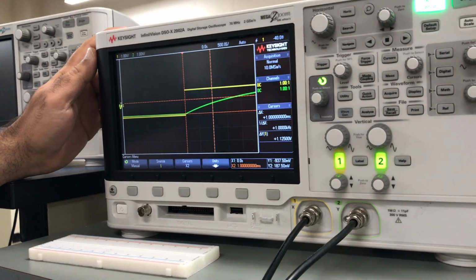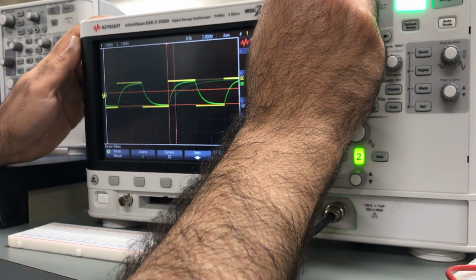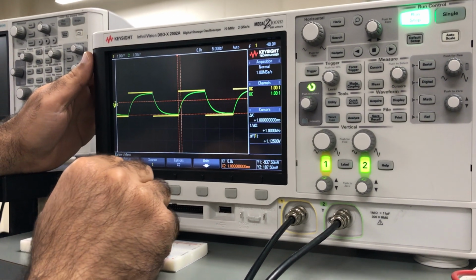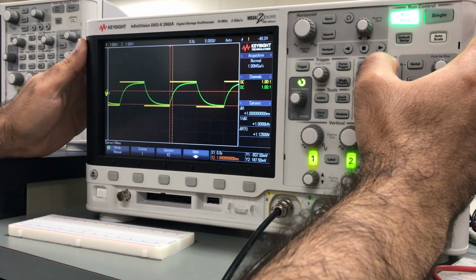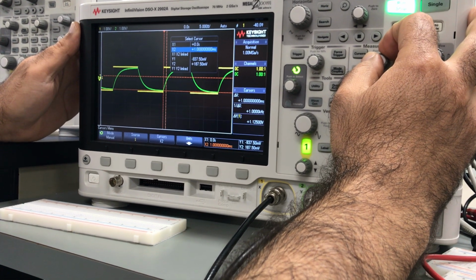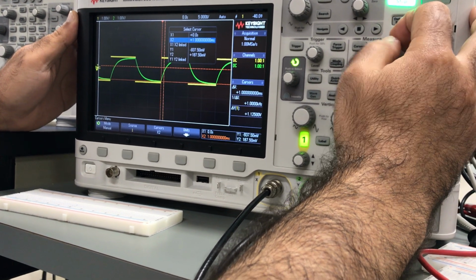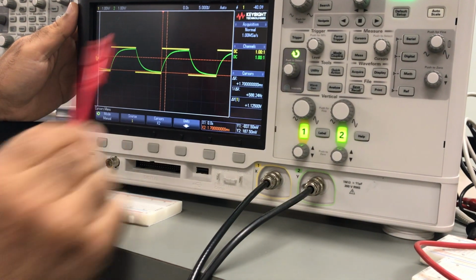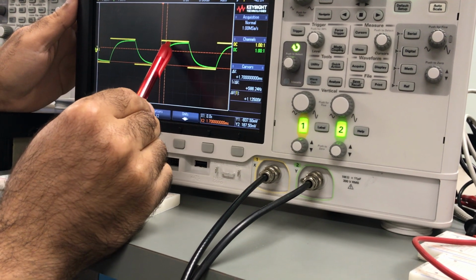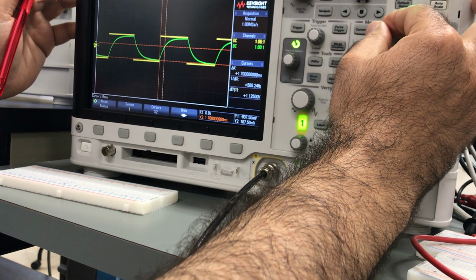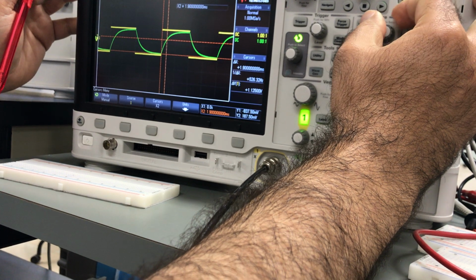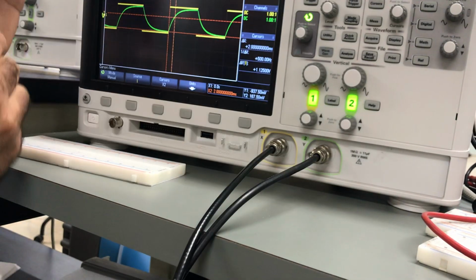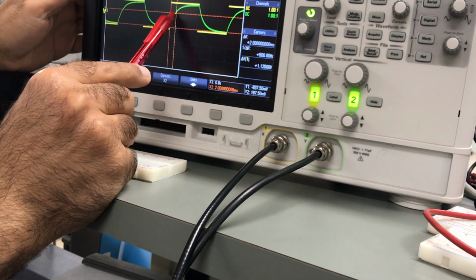See what happened. This is the waveform. I will try also, by using cursors, to move my x2 to be at the intersection between this guy and this curve. I'm expecting the time constant to be doubled because I added the same capacitor. And this is what happens. Delta x is equal to 2, which is the intersection here.